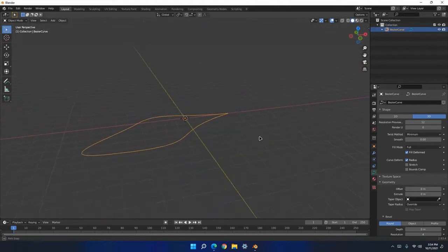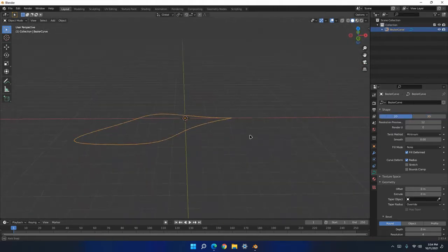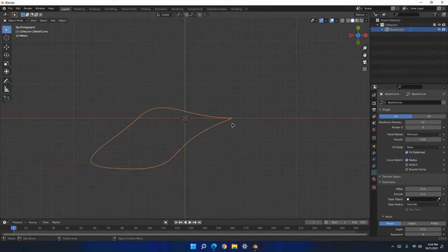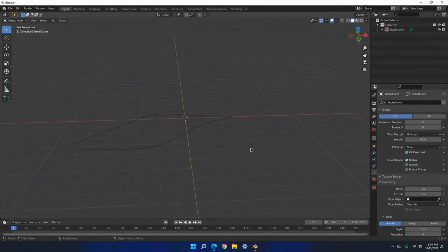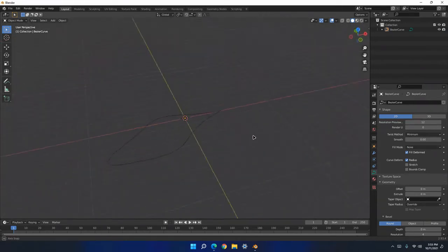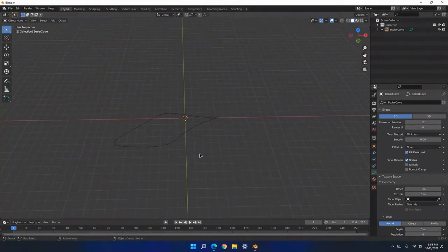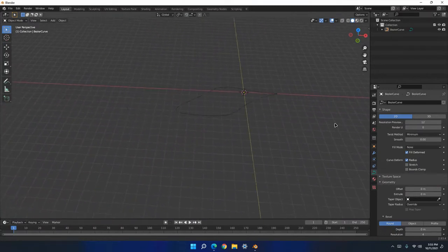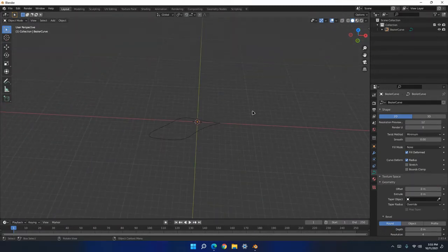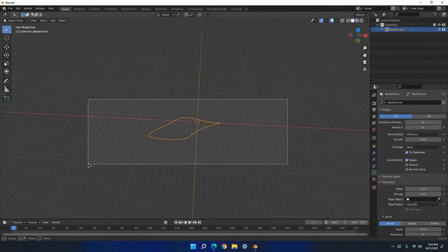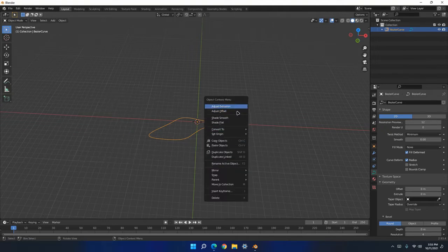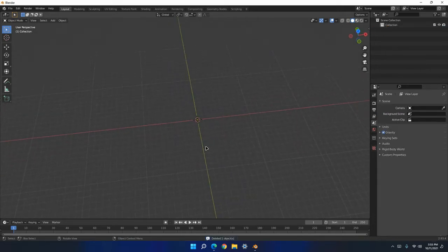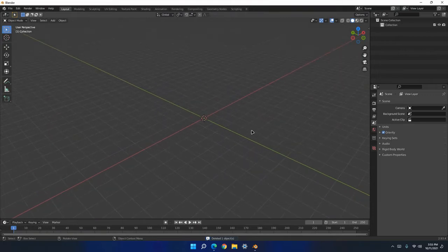If you want to edit this in 2D without having to worry about one side being taller, just press that, and now you can edit like this instead of having to be in this view. To move around, press and hold the center mouse wheel. I'm not sure if you can do it with the touchpad. To move like this, hold down Shift and then press the mouse button. To select stuff, hold the normal mouse button and drag, and to right click, just right click. Simple.